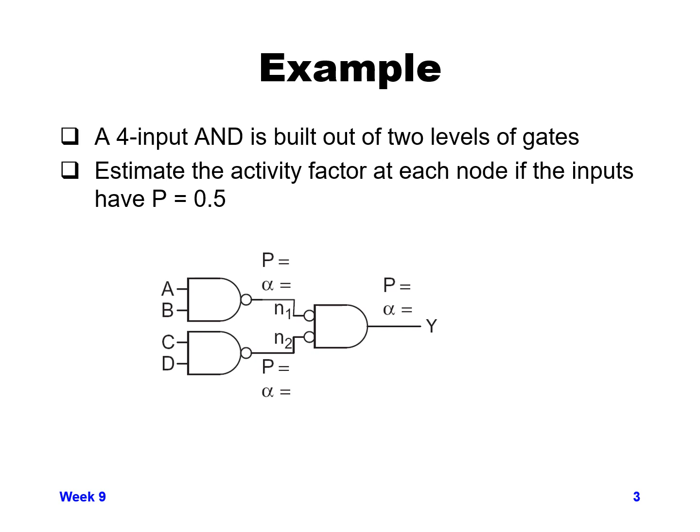So let's go through. Going through the NAND gate, if you remember, an AND gate had a probability which is PA times PB. A NAND gate, the probability that we're going to get a 1 out of it, is going to be 1 minus PA times PB. If you go back to the previous foil, you'll see that was the equation for a NAND gate.